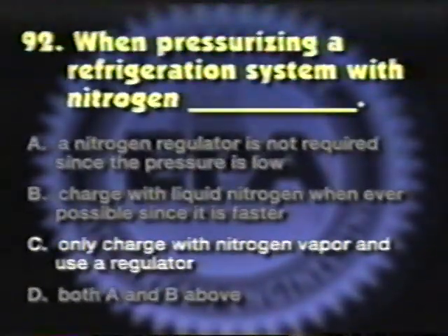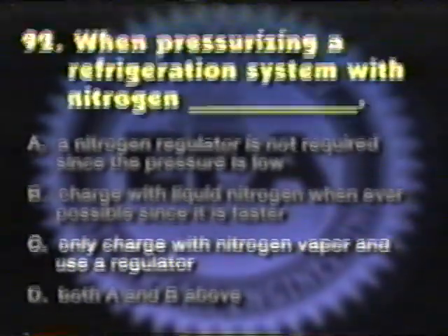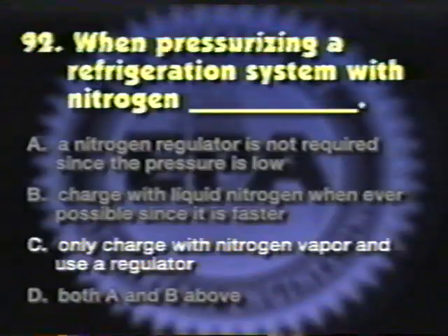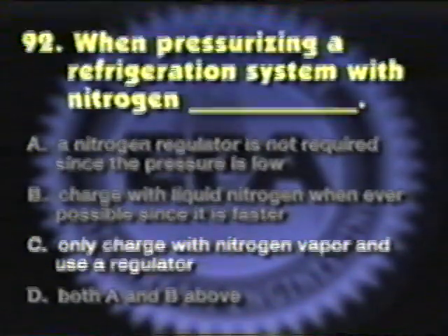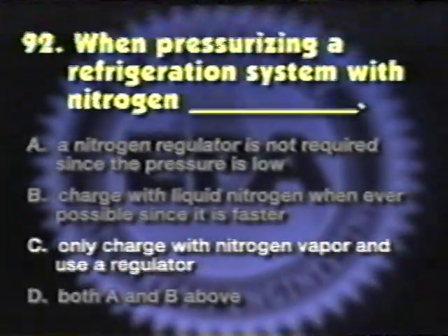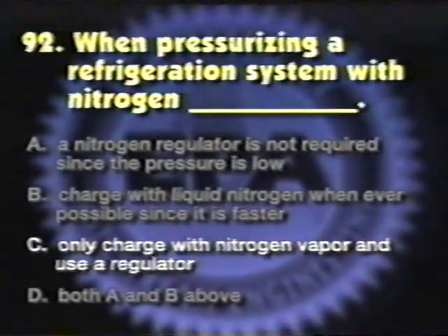The answer is C. When pressurizing a refrigeration system with nitrogen, always use a pressure regulator and never charge with liquid nitrogen. Only charge with nitrogen vapor.